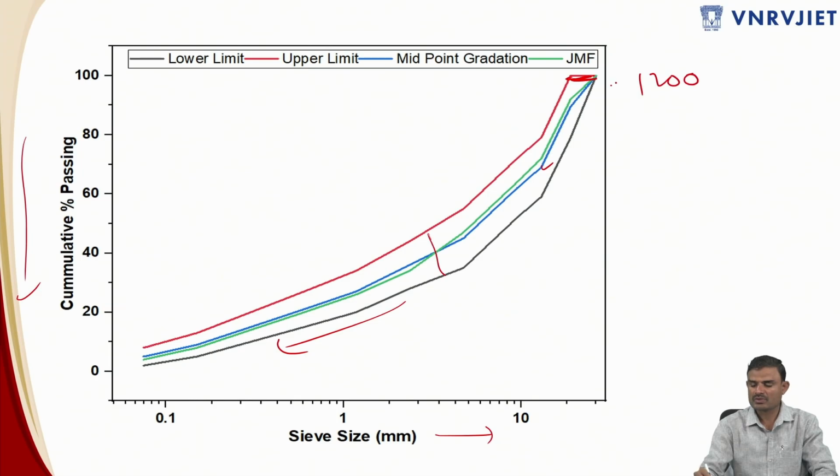So I am going to explain some small calculations over here. So 1200 grams of aggregate alone, mineral aggregate. Okay, then you have to take the bitumen content. As you have seen in the second slide, for bituminous concrete we are going to have 5 to 6%